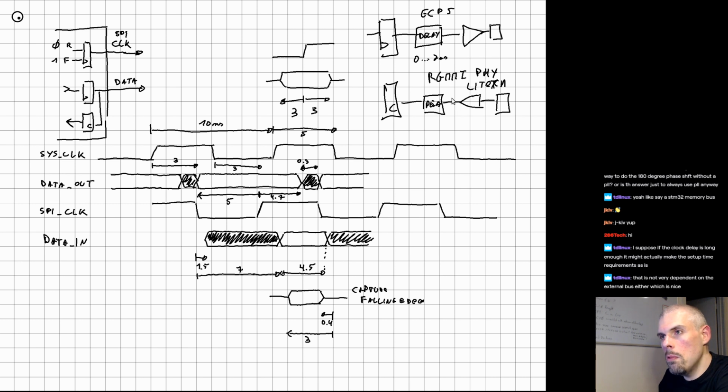Now, for input timing, you can also influence them using output delays, somewhat counterintuitively, but as you see, all the data output from the flash is relative to the SPI clock, and the SPI clock is controlled by us, right? Which means we can apply an output delay on the SPI clock output that we generate to shift the output from the flash somewhere that we can capture. That's another option.